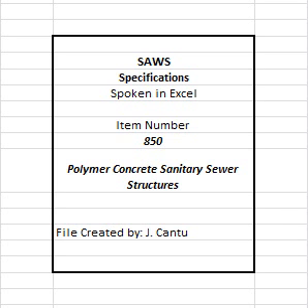C. Acceptance. Any structure which fails the initial test must be repaired per manufacturer's recommendation with a suitable material based on the material of which the structure is constructed. D. The structure shall be retested as described above until a successful test is attained. E. After a successful test, the temporary plugs will be removed. F. To ensure that the plugs have been removed, contractor shall only do so in the presence of the inspector. G. The owner may elect to simply remove and replace the existing structure with a new one.